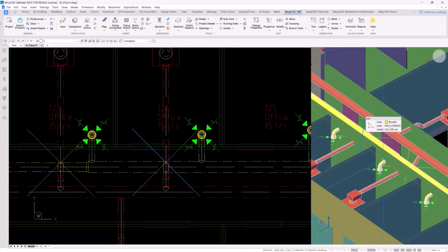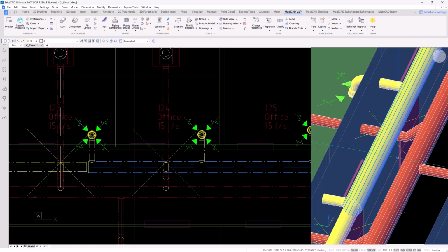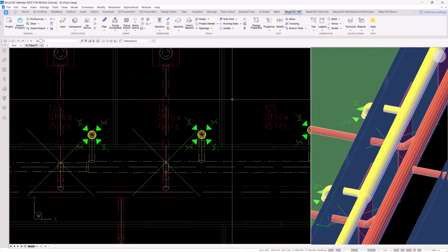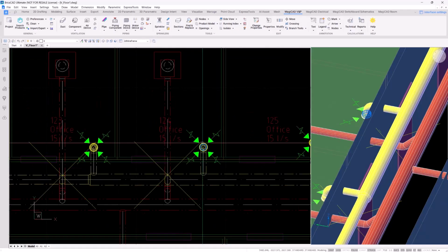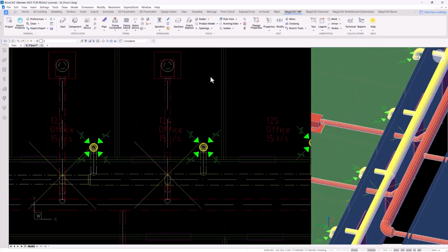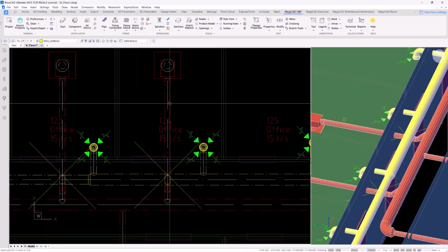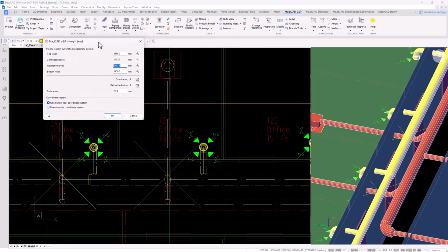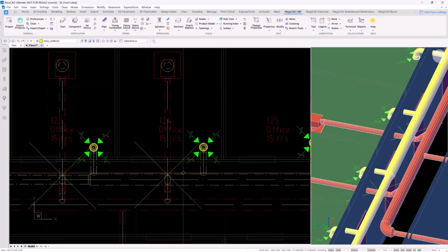For instance, here it might be difficult to see if there's a clash or not, just like that. So what we can do in this case is try and avoid the clash by moving the objects. So this horizontal duct here, we can run move and use the Z option to make a movement in vertical direction. First, we select what we want to move. In this case, we can have the tolerance there go below the bottom of the yellow extract duct. Take that as a reference.